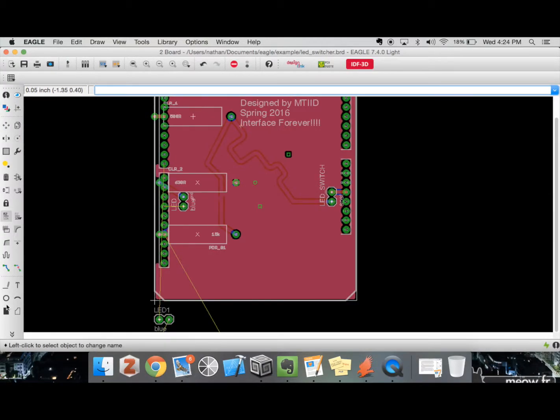All right, excellent. And then you can also place vias to go from one side of the board to the other side of the board. You press your middle mouse button while routing, and I'm using my laptop right now, so I can't really demonstrate it. But basically, you can start your trace on one side of the board, and then after a certain point, you middle mouse button click. It inserts a via for you with the correct name, and then it transfers you to the bottom layer of the board where you can continue routing.